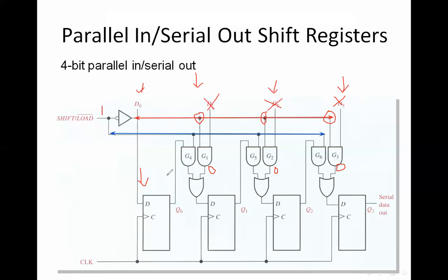So once this gets inside, now I have a 1 here. Let's say for example the value is 1 here, so my output is going to be 1. If my value is 0 here, then my output is going to be 1 into 0, which is 0. So if I have a 1 here, it is not affecting my data. Whatever is Q0, the same Q0 is coming across G4. Once it comes across G4, the same output is getting into my next flip-flop. Why the same output? Because this is a 0, so it is not disturbing my value of Q0. Understood?